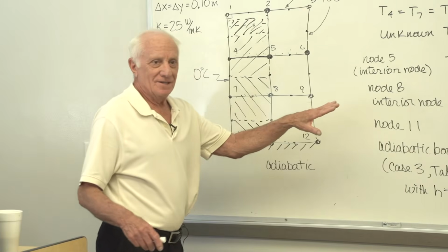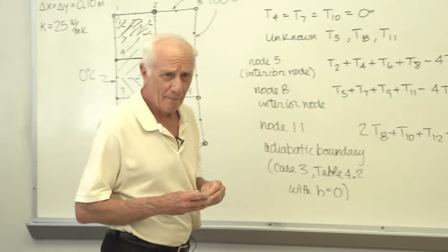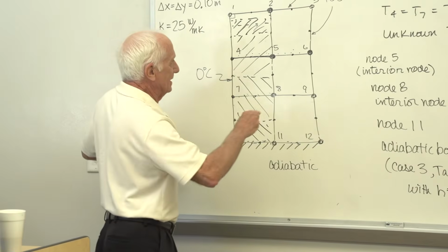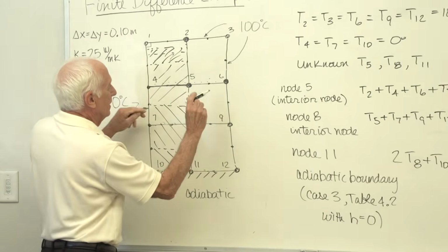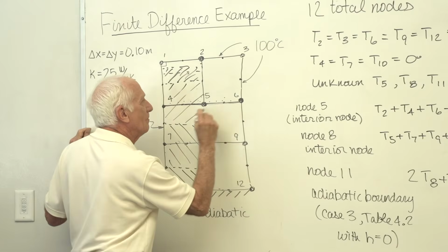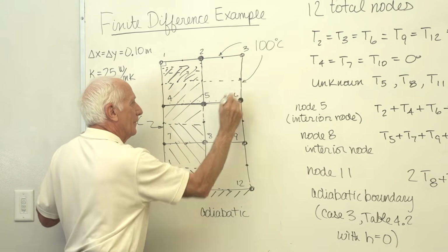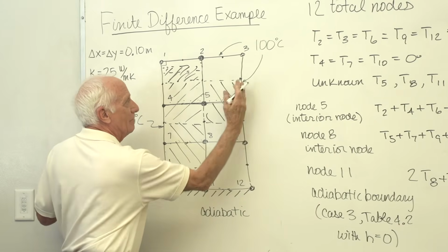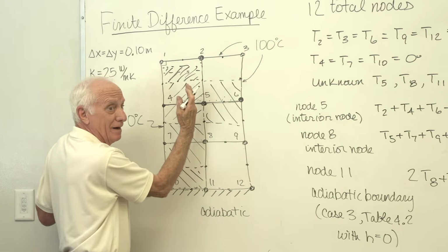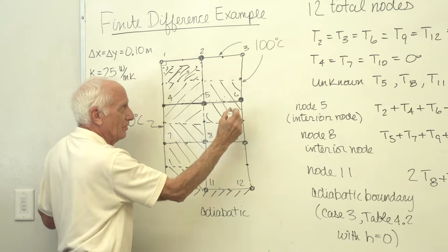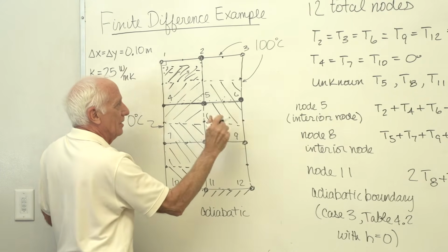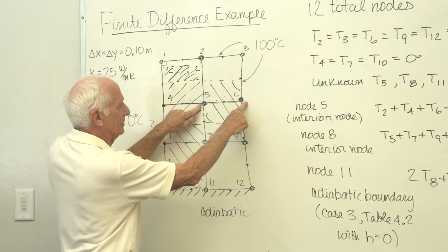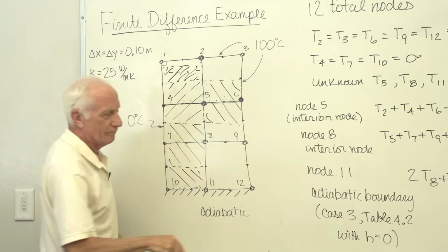Okay, any question on this then? Yes, sir. Why do we start in between the boxes again? Yeah, let's take 6 to 5. This rod replaces how much material? That much material. All the heat from here to here is called Q 6 to 5. It's replaced by a symbol, node 6 to node 5. How high is this? Delta Y. How far does heat travel? Delta X. Okay, that's how you do it.